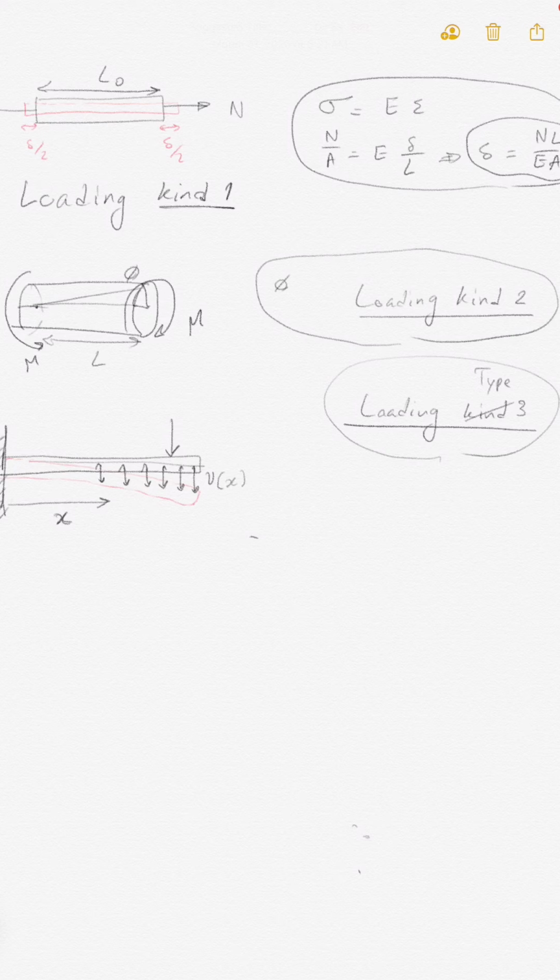Now our objective is to finish up all three deformation equations, so we will be able to solve a wide range of problems that have axial load, torsion, and bending, and that are specifically indeterminate. The sole purpose of deformation analysis is to get additional equations that we can add to the basic equilibrium equations to be able to solve the indeterminate problem.